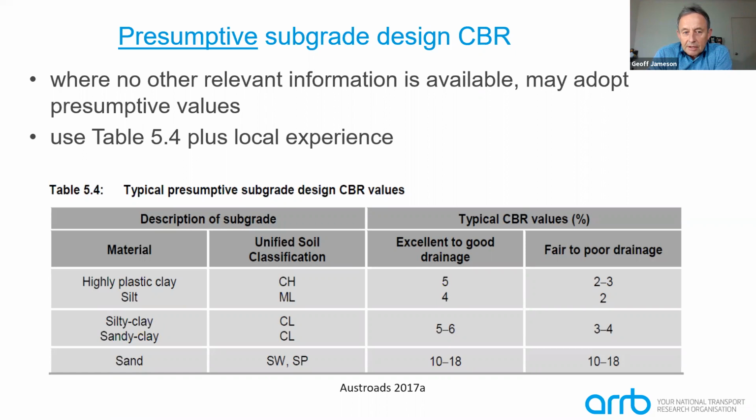We've provided in the guide some presumptive values that are based on experience, basically, of what designers have used according to the material type, the material classification, whether the subgrade is a heavy, highly plastic clay, a silt, a sand, a sandy clay, for example. And these are really based a lot on experience and a lot of past laboratory testing.